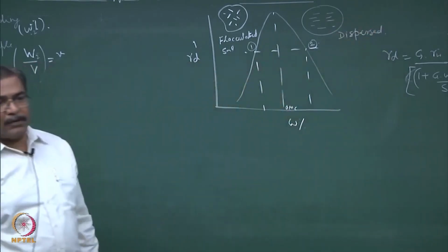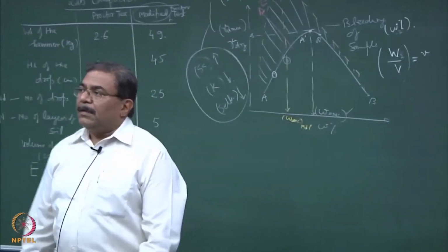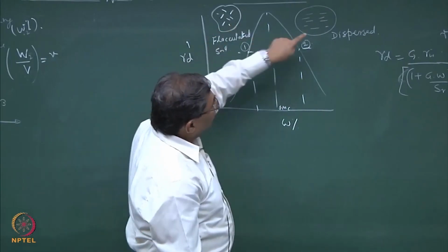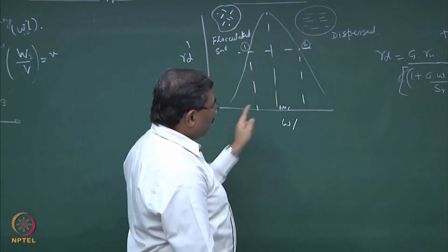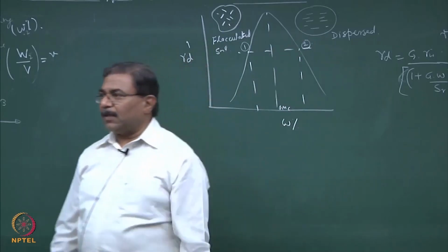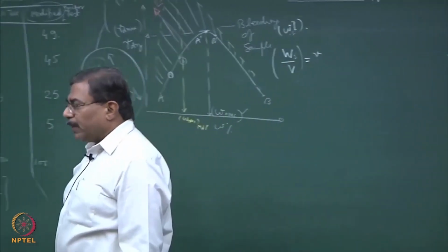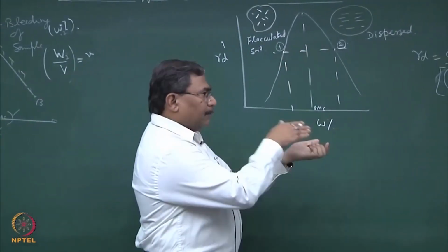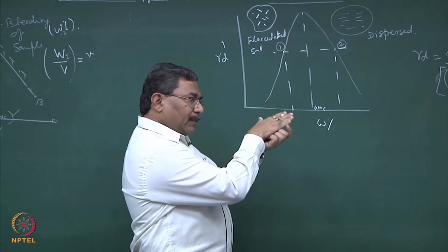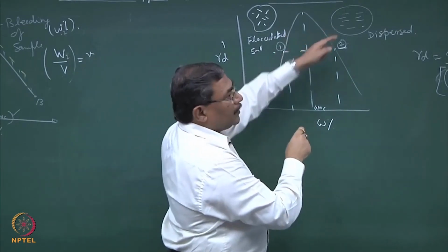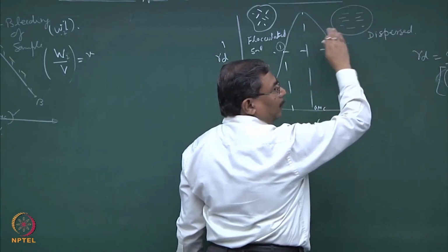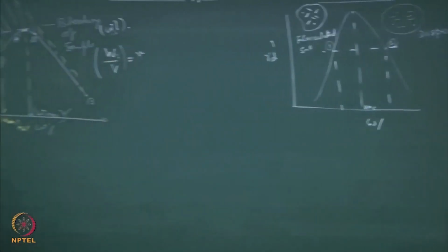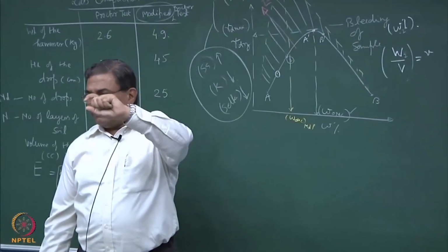You remember, we have talked about this grain structure of the soil. From a disorderly state, the grains have become ordered by adding more moisture. So, what does moisture do to the soil? It acts as a lubricant. Fine. So, the more and more moisture you add, the particles, the grains start slipping over each other, they become more ordered, you are compacting them. So, they have got aligned like a ferromagnetic material, where the ferromagnetism takes care of the alignment of the magnetic poles which get created in the system.